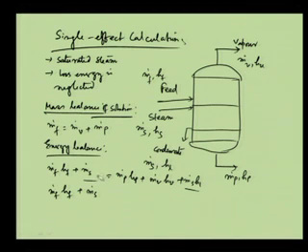This is h_s. h_s minus h_l will be the lambda. So, m dot into lambda_s, that is the latent heat of condensation of the steam, will be equal to m dot_p h_p plus m dot_v h_v. So, this is the general mass balance equation that we can get.